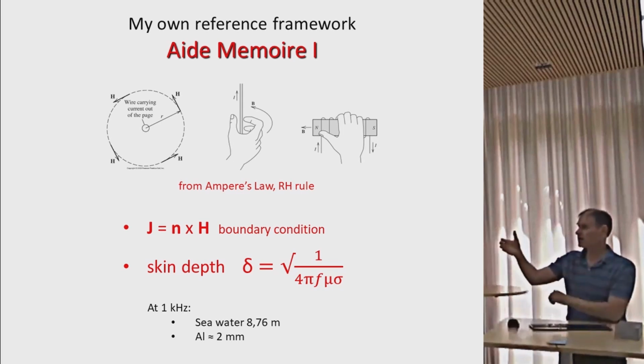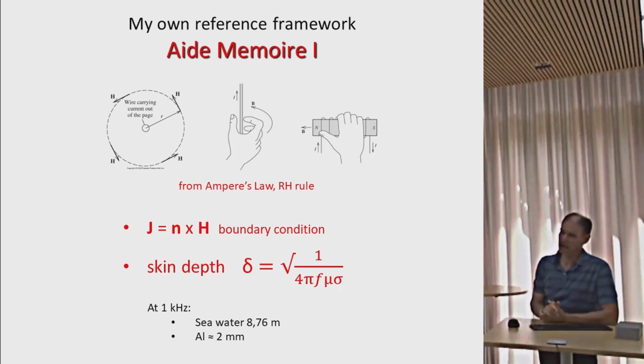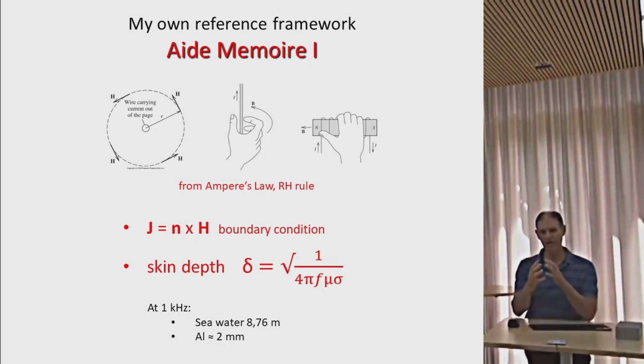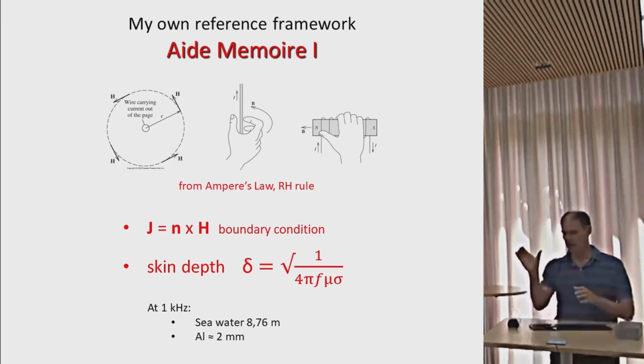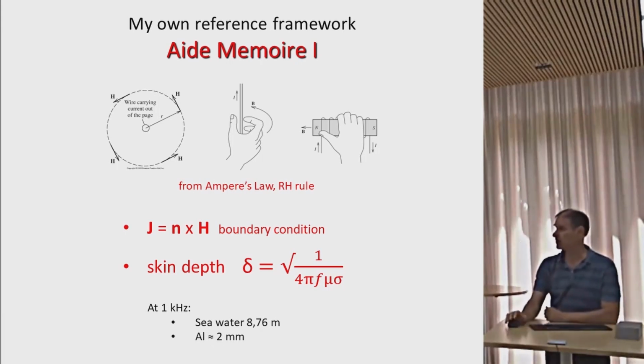It's called the right-hand rule, but this time you'll see the current creates a B field, and the B field and H field are identical, except that the B field also incorporates the medium magnetic material, mu. So B and H people use interchangeably, but B has got more to do with the magnetic environment in which you're working, and it also shows you that current in a direction causes a magnetic field circulating around it.